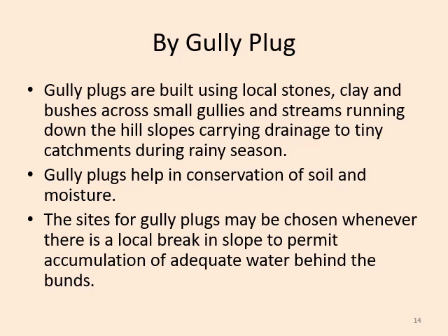The sites for gully plugs may be chosen whenever there is a local break in the hill slope, to permit accumulation of adequate water behind the bunds. So the suitable site for gully plugs may be chosen when the slope has a break. The slope is not continuous, where we can collect or accumulate the adequate runoff water coming from rainfall behind the bund.